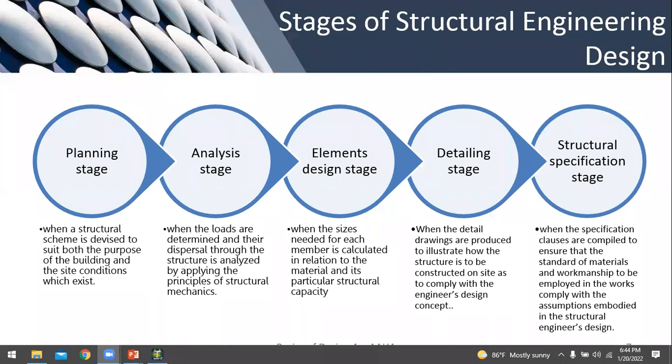Some people think the roof floor columns don't have much load, so we can provide minimum reinforcement like 4T12. That is also totally wrong, and I will show you when the analysis portion comes. When you think about the top floors, due to the connectivity and the freedom of movement, the bending moment is very high at the top of the top floor columns. The axial force is low, however it has more bending moment, so the requirement of reinforcement is high.